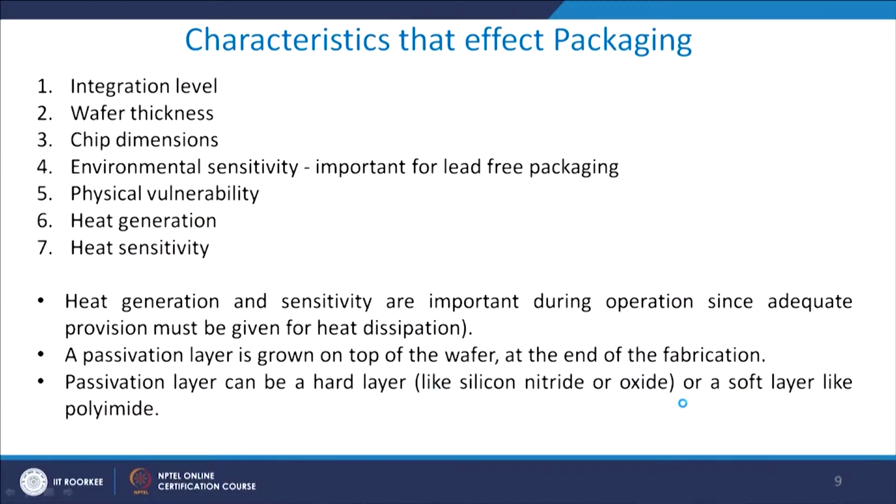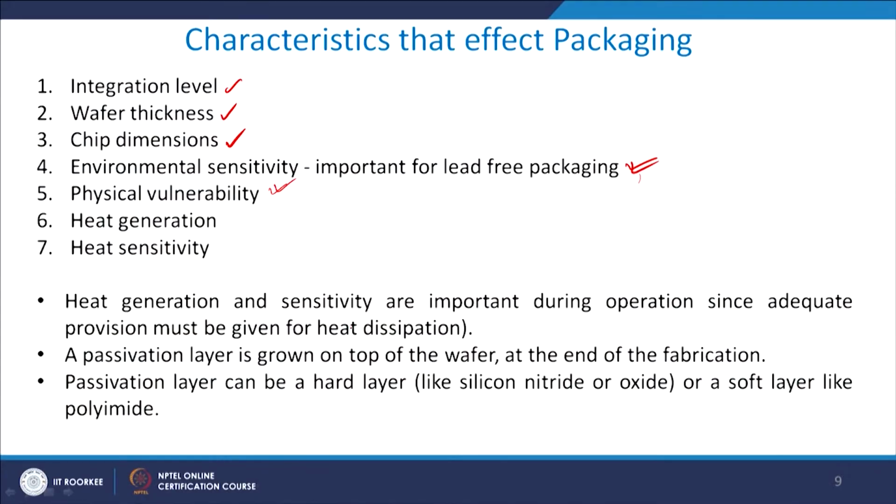What are the characteristics that affect packaging? Well, of course, what type of packaging you will be using will depend upon the type of integration level you are using. Similarly, how much wafer thickness you are using, what the dimensions of the chip are, and then environmental sensitivity. For example, people generally do not like, for obvious reasons, arsenic and lead as part of the packaging technique, and therefore it is not a good idea to have these materials in the package. And then its physical vulnerability, because of how prone it is to mechanical instability.